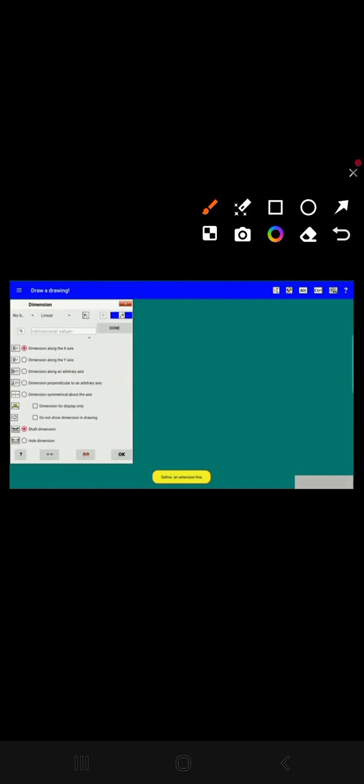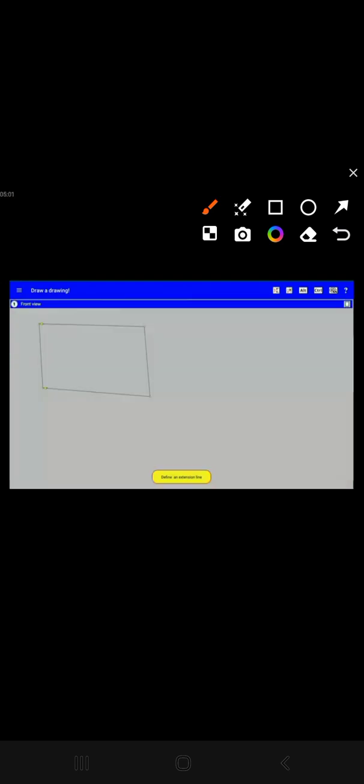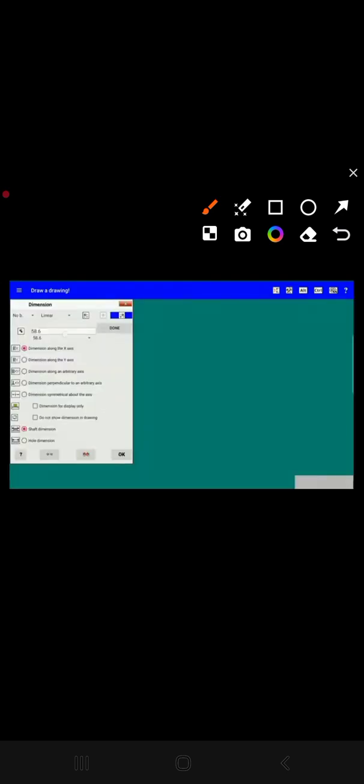Please note that the Done button of the Dimension Input Control dialog has become available, but it is too early to use it, since the dimension has not been fully entered yet. Exit the dialog by clicking the OK button. We mark 2 points of the rectangle. The application calculated how far the first support points with smaller and larger dimension coordinates are now from each other.